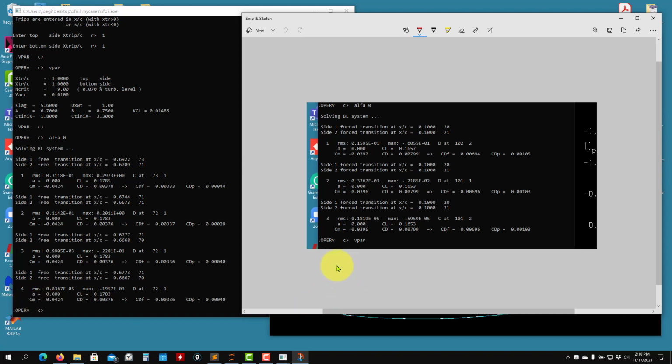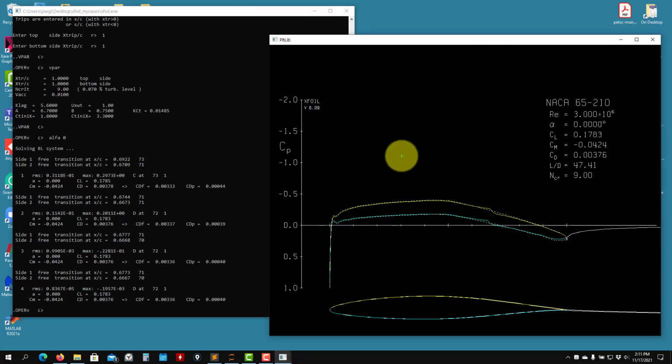Because to compensate this pitch down moment, we need to add a force in the tail, or if you have canards, you will need to add some force there, and usually to trim the airplane, that will add drag, but also you might lose some lift. So probably as you start to do the whole configuration, at the end of the day, even if you produce more drag, this will be better because you have lower trim drag. So always look at that component. Moment, all coefficients are important. So that is what I wanted to show you.